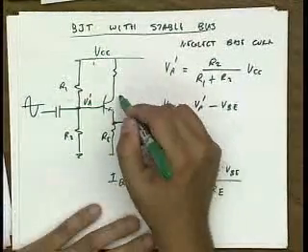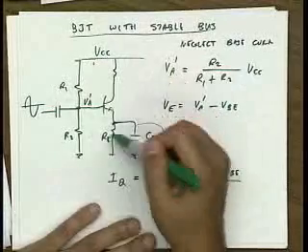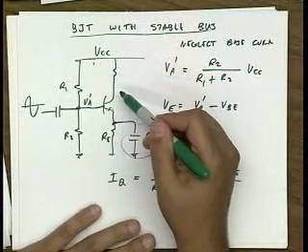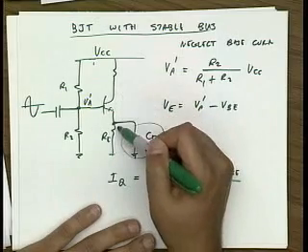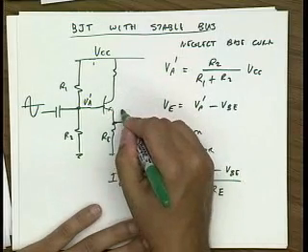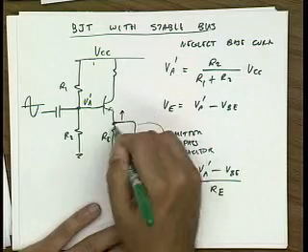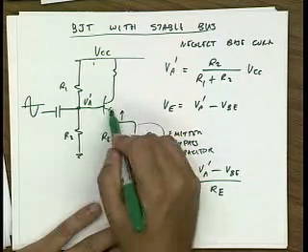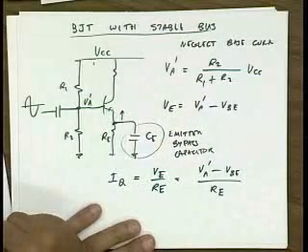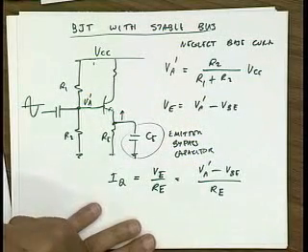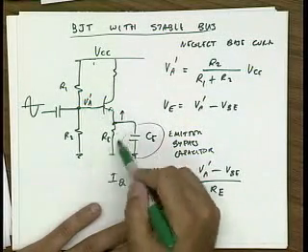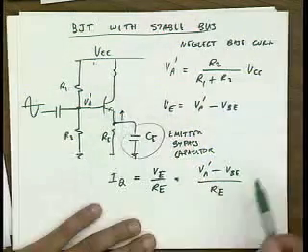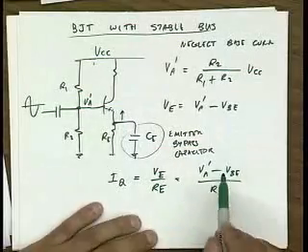This large signal will generate even order distortion through this nonlinearity, which would tend to increase the DC current. As the DC current increases, that would increase the average voltage here, which would reduce VBE, which would tend to decrease the DC current. So intuitively, the action of RE is negative feedback for the bias current, which forces the current to average out to this value.